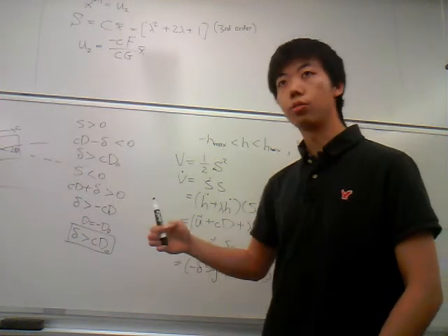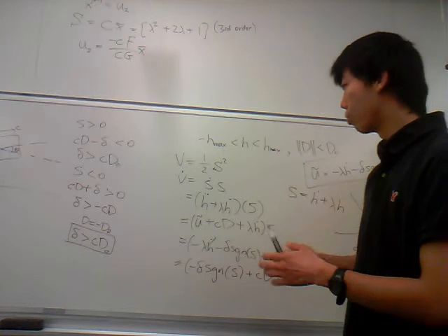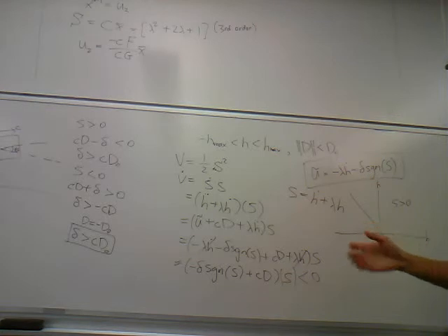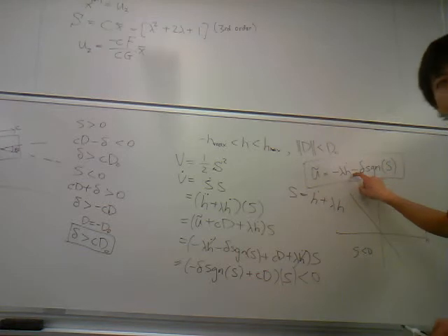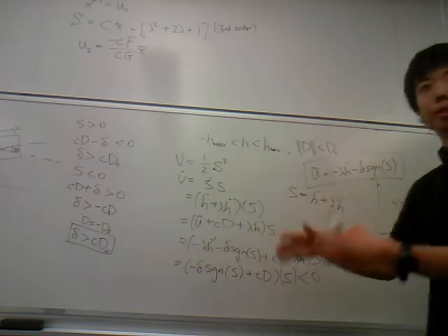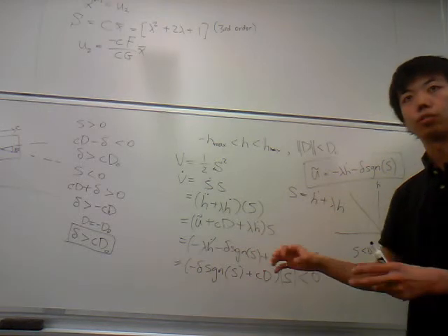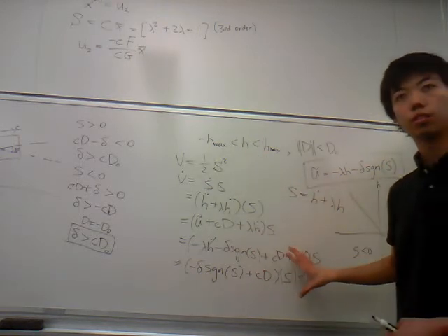To design the controller, we ignore that disturbance because we're going to assume that this extra term is going to be robust enough to kick all the disturbances back into place. But to prove that this controller is actually stable using the real plant, that's when we have to put in the real plant and our controller, and when we do the Lyapunov analysis.